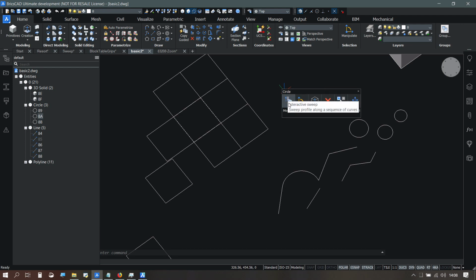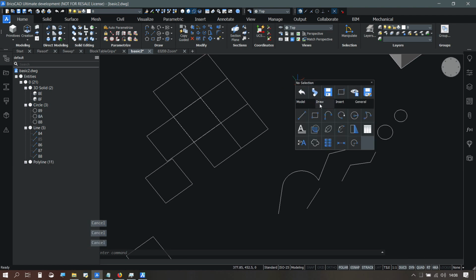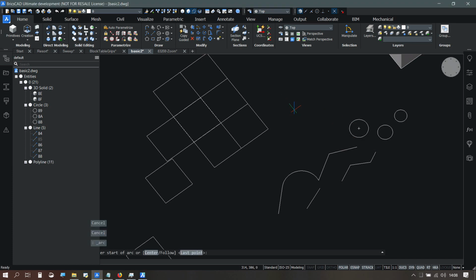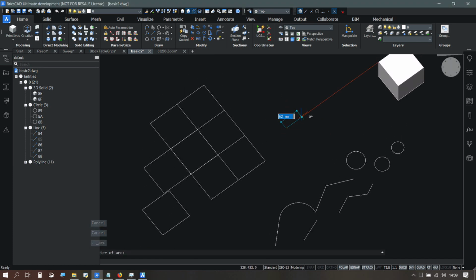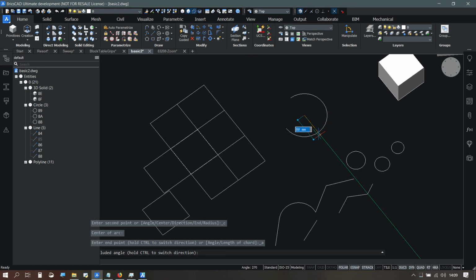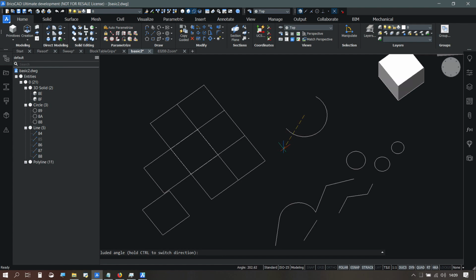While we are discussing small features, another small feature is when you draw an arc, then the rotation direction may be as you want it, but sometimes you want it to go the other way. And then all you have to do is press the control key, and it goes the other way. Now I let go of the control key and it goes back. So, small thing, but saves time.